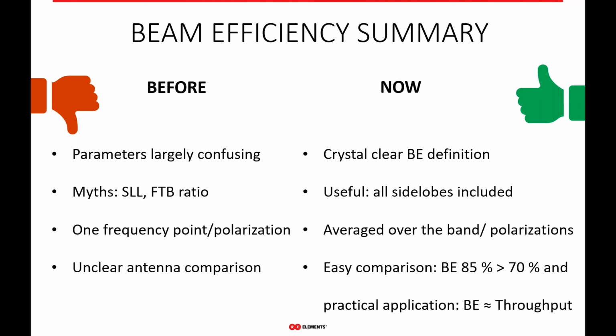So always ask whether a parameter is single frequency or wideband in the WISP industry, right? When you're looking at a performance parameter of an antenna, you should ask the manufacturer you're buying it from whether that parameter is at a single frequency or is a wideband parameter. Because this really is a must: the spectrum is shared by many, so wideband performance is vital to your success.